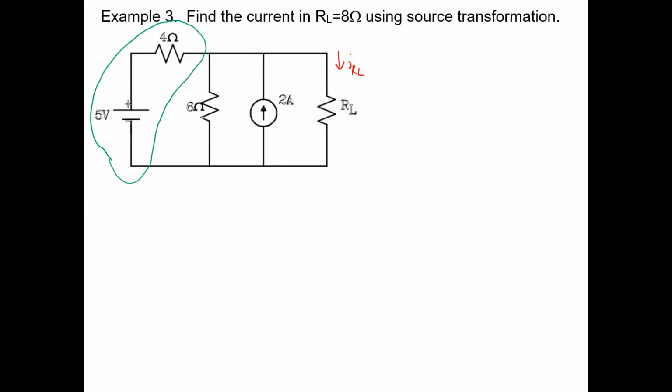So you could transform this into a voltage source in series with a resistor as well. I wouldn't write this because we're not going to do this transform until later, but you could turn this thing into a resistor in series with a voltage source. I'm going to erase it right now so you don't have to put that down, but it is something you could do. It just doesn't really help us at this point to do that transformation first, because then we're going to have 2 parallel branches of voltage sources in series with resistors, which doesn't really help us reduce it any further.